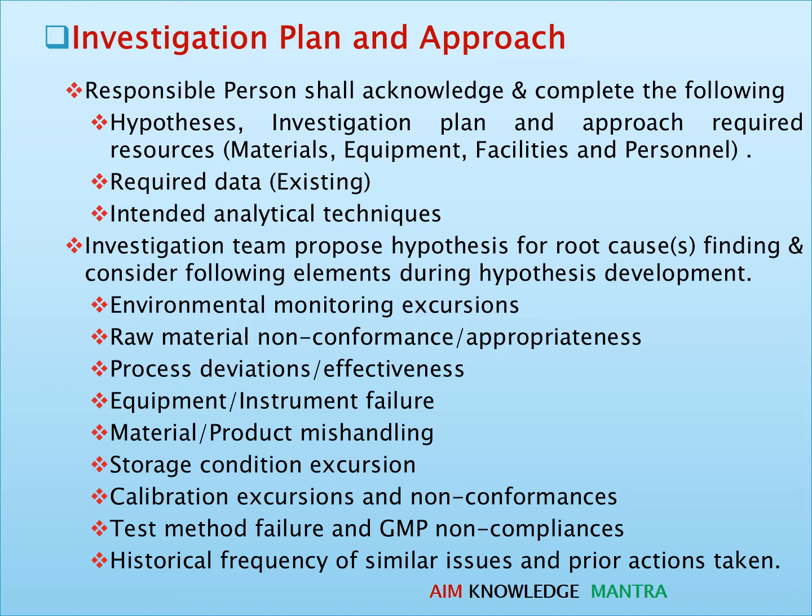The investigation team proposes hypotheses for root cause findings and considers the following elements during hypothesis development: environmental monitoring excursions, raw material non-conformance/appropriateness, process deviations/effectiveness, equipment/instrument failure, material/product mishandling, storage condition excursion, calibration excursions and non-conformances, test method failure and GMP non-compliances, historical frequency of similar issues and prior actions taken.